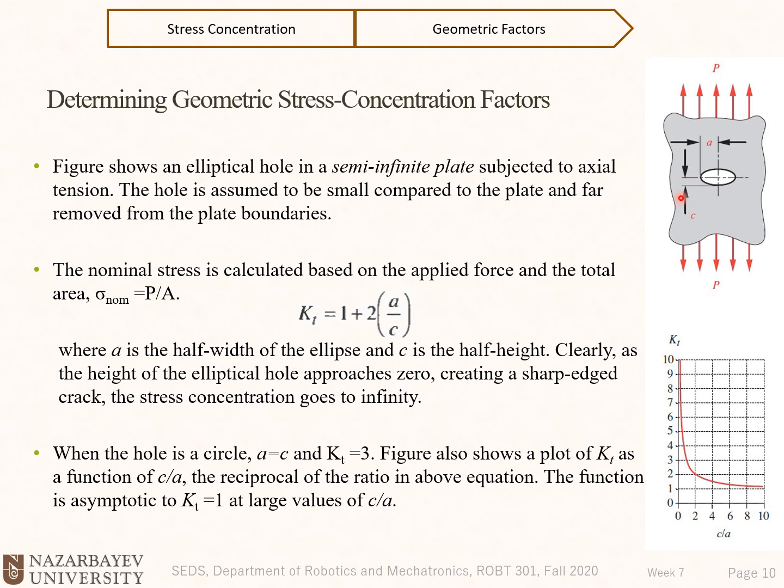But if C goes to 0, then the crack could be opened by the forces, and at the tip of the crack we'll have a stress concentration, and basically the stress could go to infinity. So here we have a static force, and we managed to find a geometrical stress concentration factor.